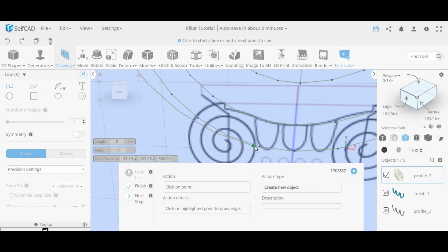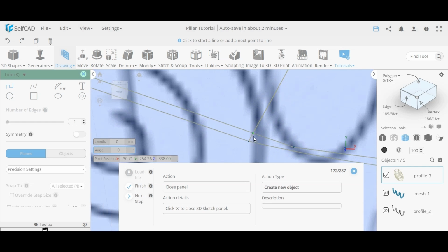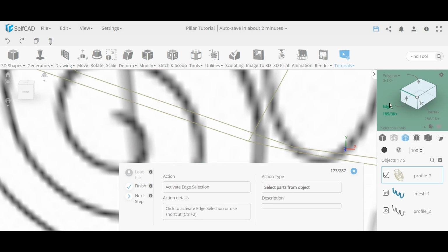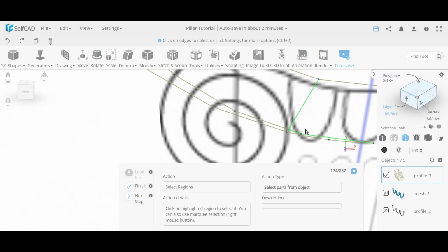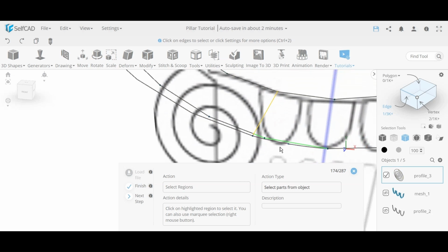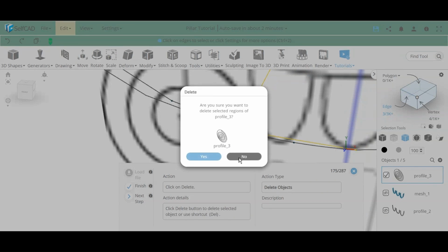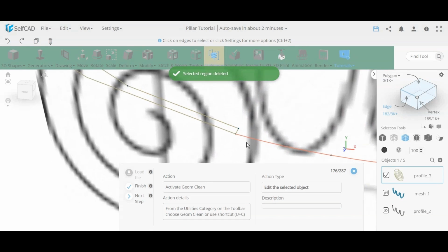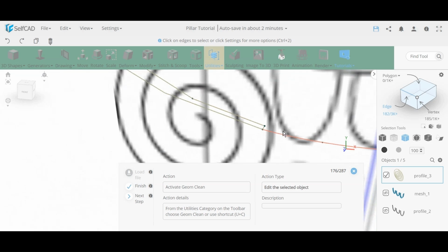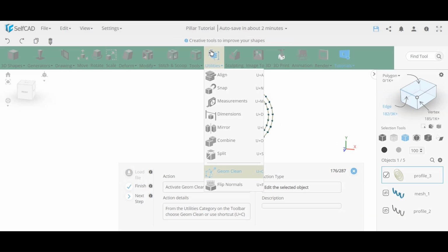So we're going to draw here a line simple here and over here. Now the reason we click over here, just because we have a vertex over here, it's easy to snap. And we wanted actually only this small tiny segment over here, but we're going to clean this up now. So we added this. Now we're going to go to edge mode to select an edge, and as you can see, we actually remove this edge plus over here these edges over here, and we just click delete, so it's removed. So you can see what happened over here, that we ended up having a line over here closing it, and this is just a technicality to keep it manifold, not part of design, but it wouldn't hurt the design.